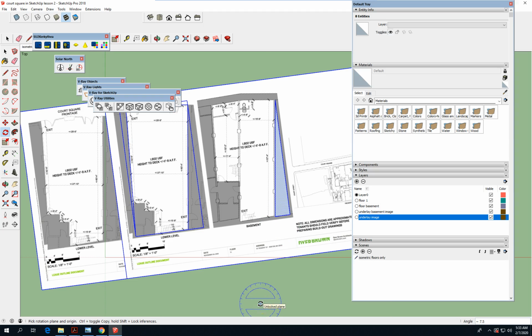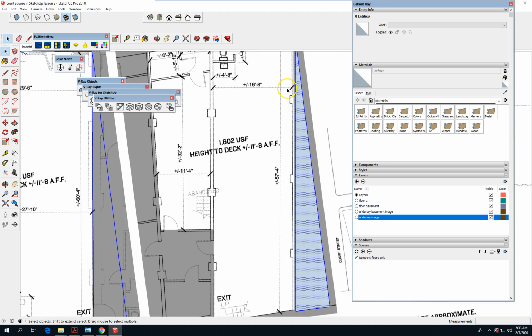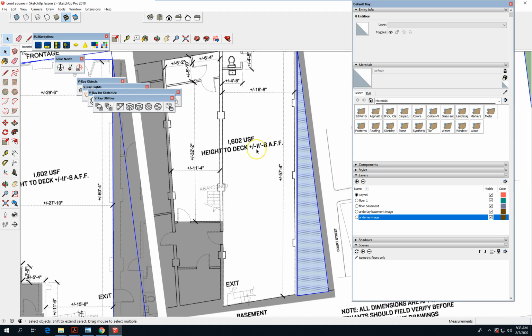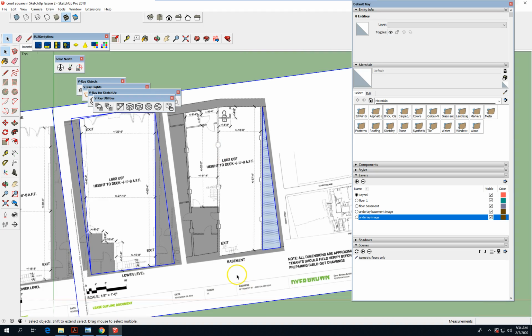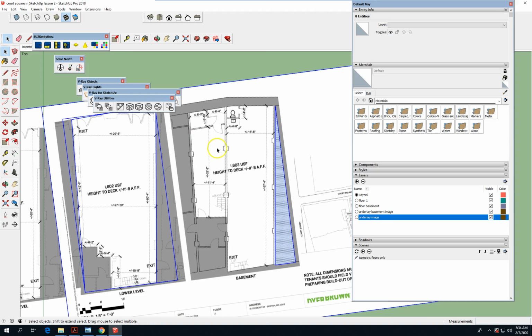Now it's really important to understand what I've just done, because what this allows me to do is draw these columns orthographically. All right, not all of them. There's a slight radial disposition of that wall, so these are not square. But these are square to my drawing. Enough said. I don't want this to get too long, so let's start modeling columns